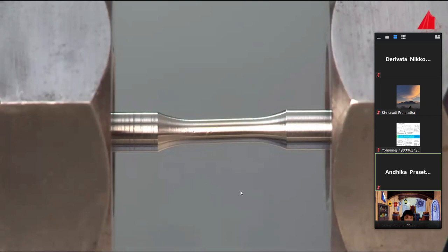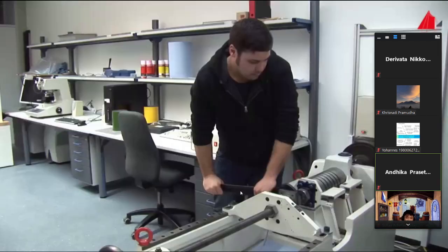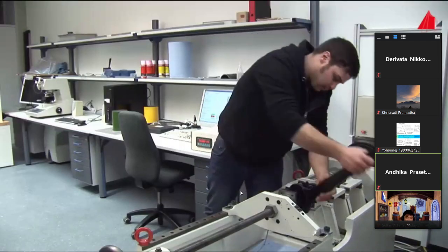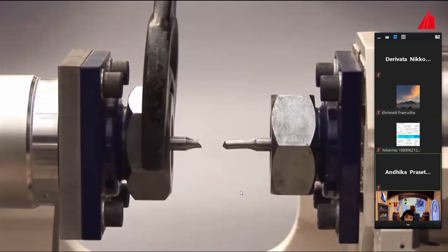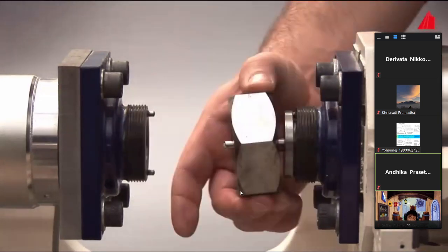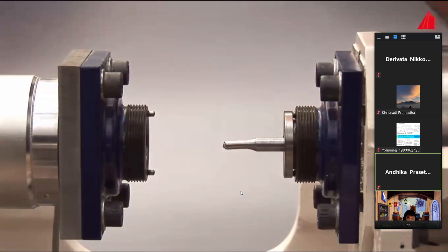In reality, however, several cracks have already developed starting from the surface, the so-called fatigue cracks. With each load cycle, they grow a bit further into the specimen. The biggest crack gains the upper hand, grows the fastest, and finally leads to fracture after 381,000 load cycles. The first test is finished. The material tester removes the fragments cautiously and inspects the fracture surfaces.